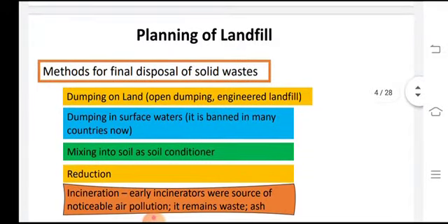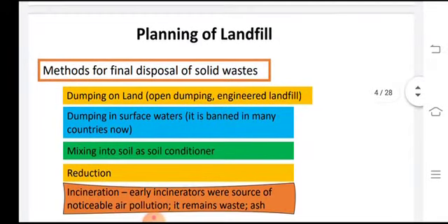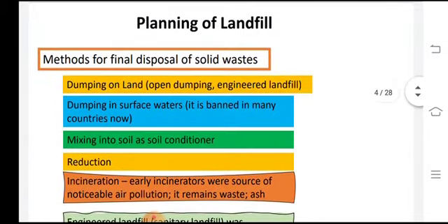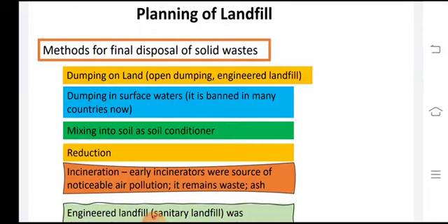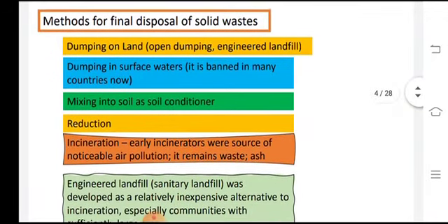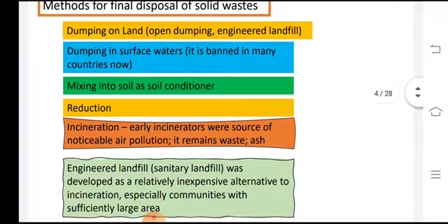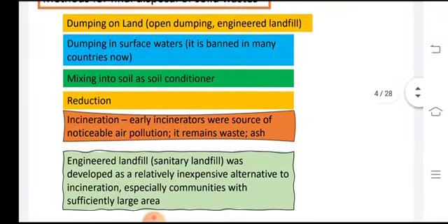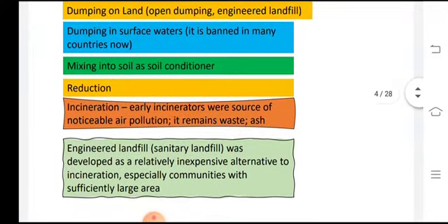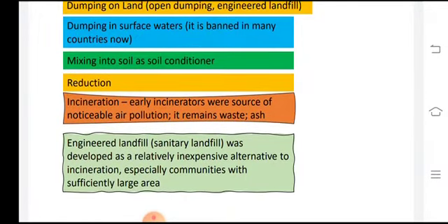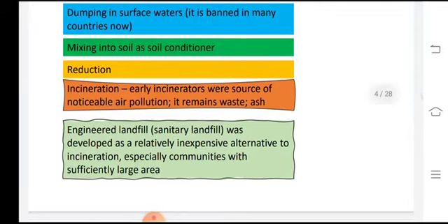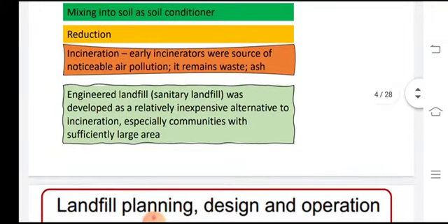It is either going to leach wastewater, or it is going to have some chemical reaction and release some gases. In both cases it must be monitored, and the amount of gases being released must be measured and controlled. Again, the wastewater collected from the leachate is going to be treated. It is pumped back to the surface, and it is treated by different wastewater treatment techniques.